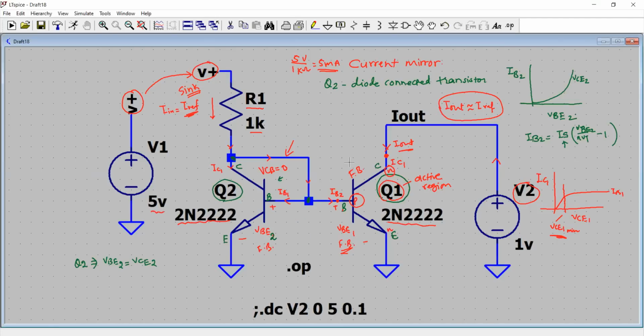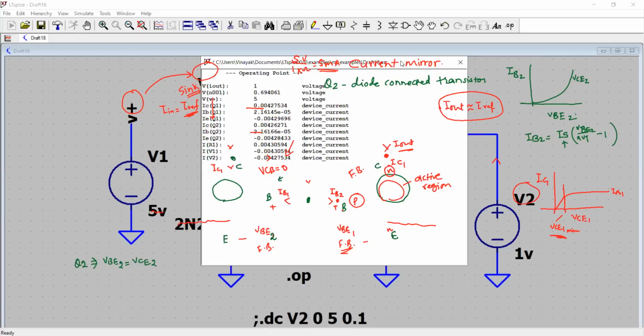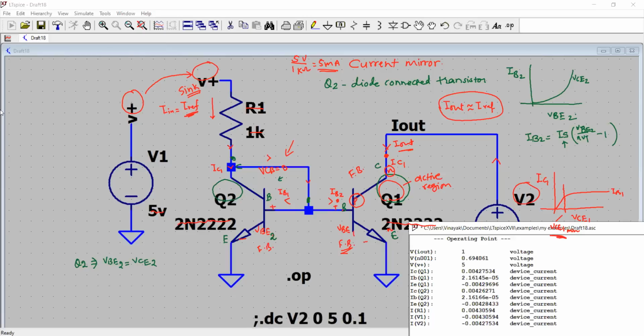So having done that, now we want to understand, click run, and our results are out. And here now we are all set to understand one by one all the points. So let's say your voltage here is 1 volt, so the voltage at the collector actually is greater than the voltage at the base, you see, but I said you want it to be smaller than the voltage at the base, so that this junction is forward bias. So we'll see how it goes.